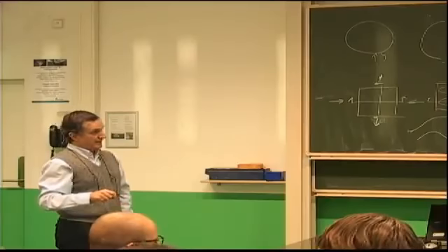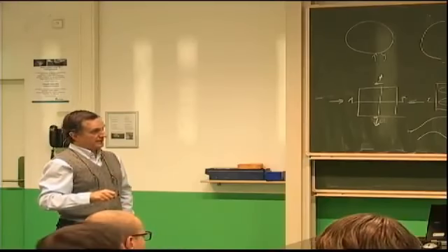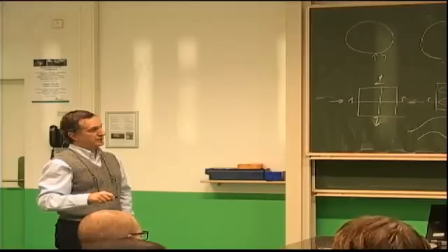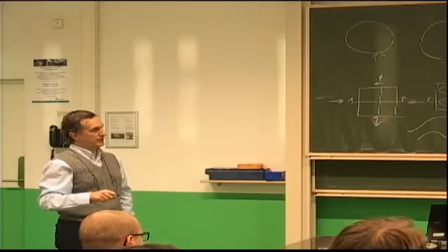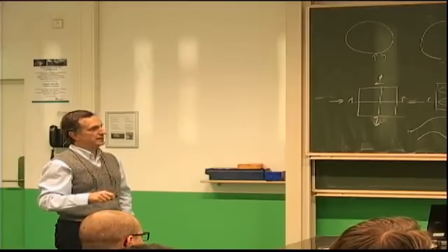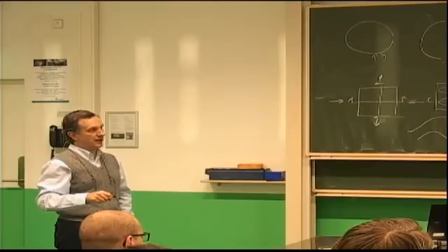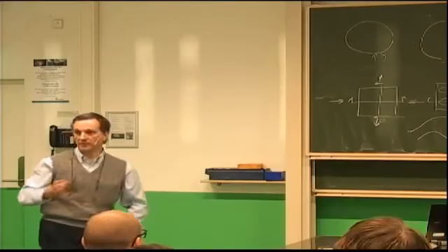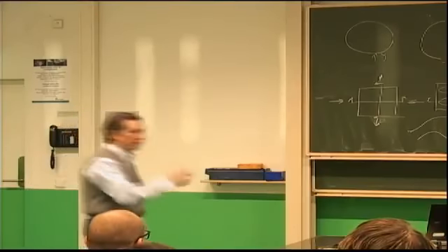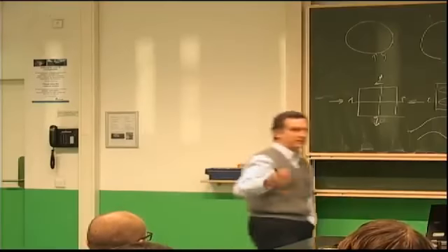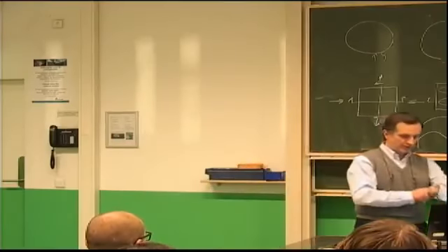Still, after I set N equals 1 in this expression, I still have M. Since there is M squared at the denominator and M fourth here, I'm left with an M squared here. The M squared cancels the second term, M squared in the middle, and it becomes an M squared at the denominator. So there will be some cases where M equals 1 or 2 would give you the lowest, but some cases where M equals 15 or 20 will give you the lowest buckling load.